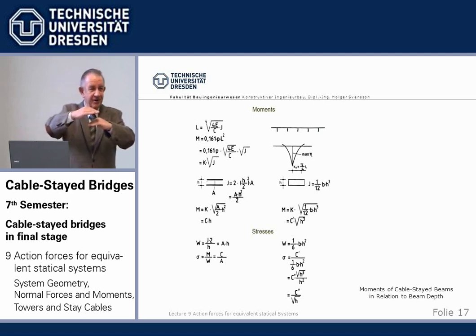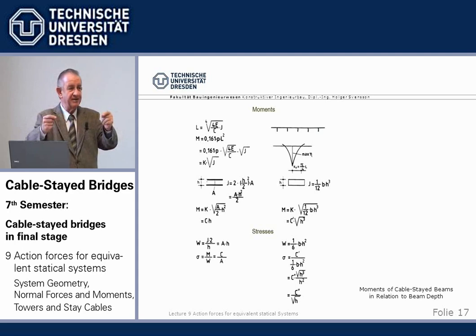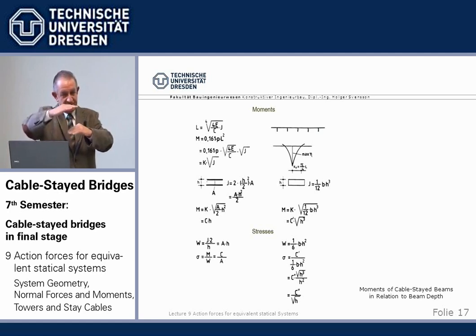Yeah. The limiting condition, however, is the buckling. I cannot have less depth or less bending stiffness, so that I still have sufficient safety against buckling, or practically speaking, I limit my increase of stresses due to non-linear theory. We come to that. But we can get rather close, and I will show you examples. You've seen bridges which are very slender, and the basis is this. The stresses do not increase within certain limits if we decrease the beam depth.